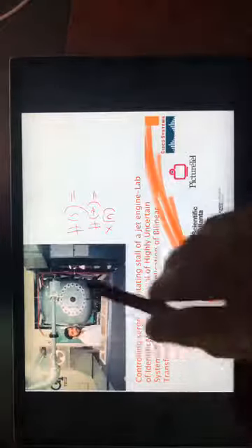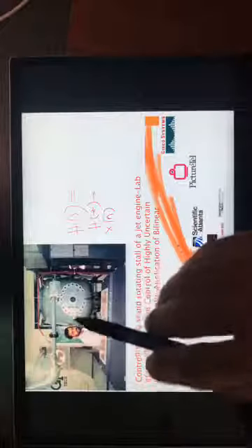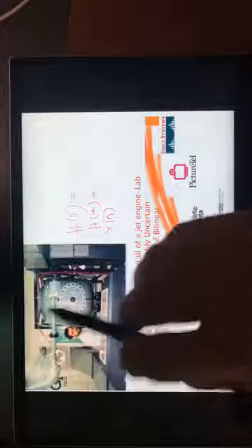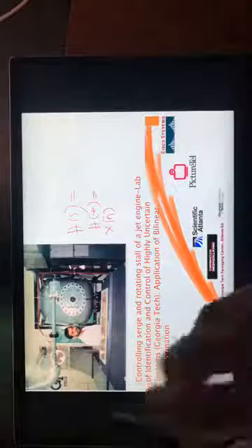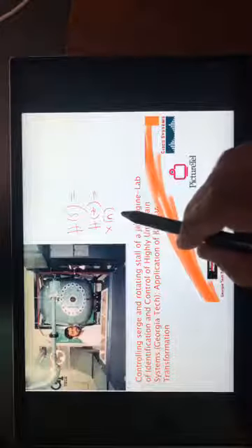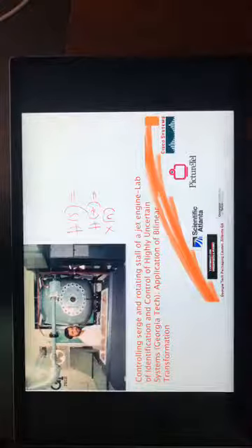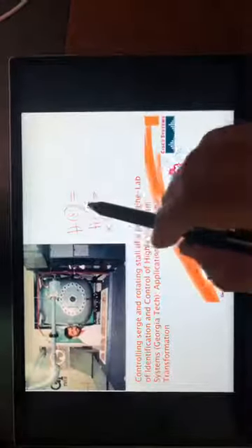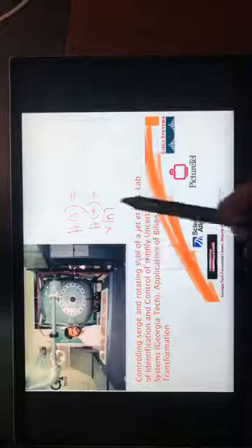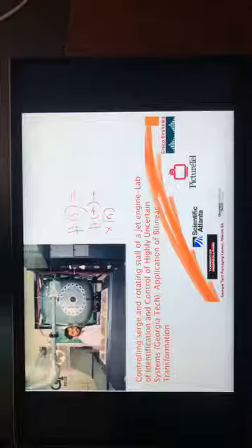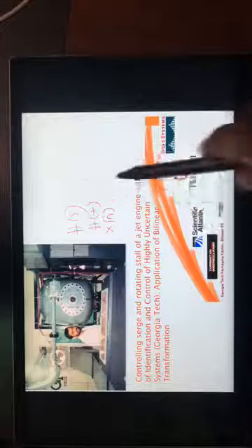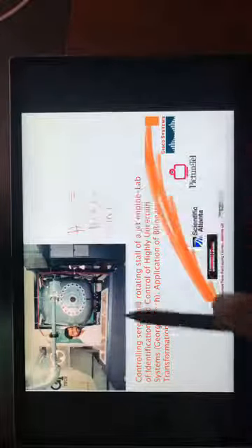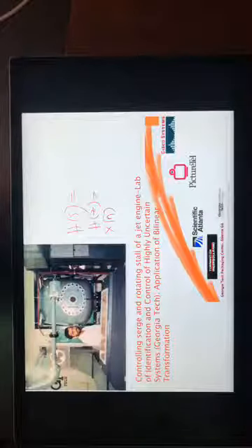They were testing different pressure sensors in different locations of the compressor and finding out which one was the best. For every pressure sensor, they could bleed a valve, and for every valve there was a difference equation like this. So I had such a simple job: I would take H of S, use the bilinear transformation, convert it into H of Z, and put in a difference equation. I would work 3 hours in this lab and make a lot of money for them, because they had no clue how to convert an H of S into a computer program. So I was doing that for them.